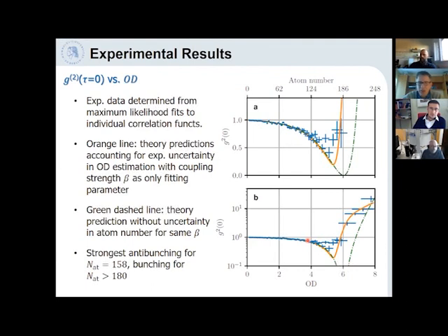It's actually done by modeling the fiber pulling process. We have very stable translation stages that stretch the fiber, which are computer controlled. And we have a very stable flame that heats the fiber and has a constant width. The modeling only uses one underlying principle, which is volume conservation, because the glass gets soft, but it doesn't evaporate.